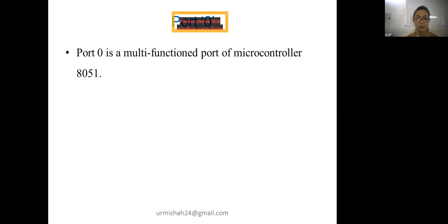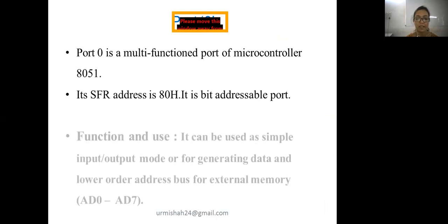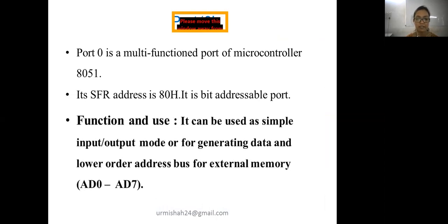Now port 0 is used for multi-purpose. Its SFR address is 80H and it is a bit addressable port. SFR address means special function register address.